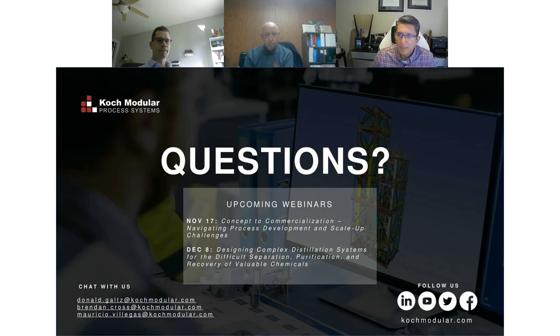Great, thank you. One last question is, Koch's liquid extraction technology literature indicates that miscible columns can have up to 10 stages per meter of tower height. Are these theoretical equilibrium stages, or does a stage efficiency need to be applied? If so, what is the stage efficiency typically?